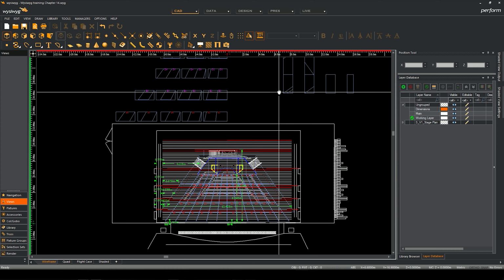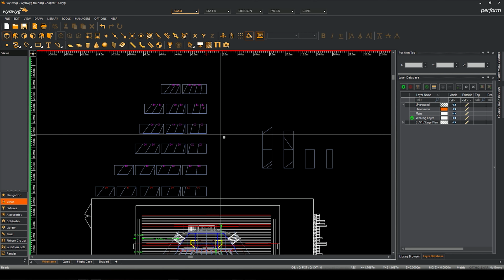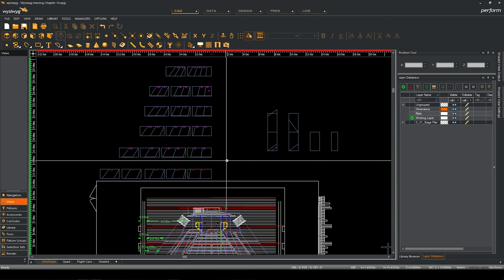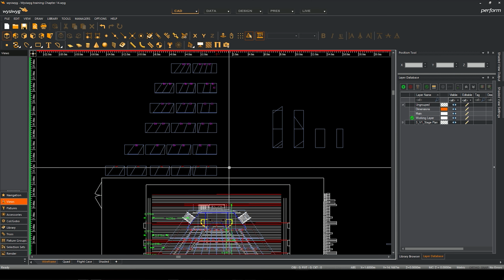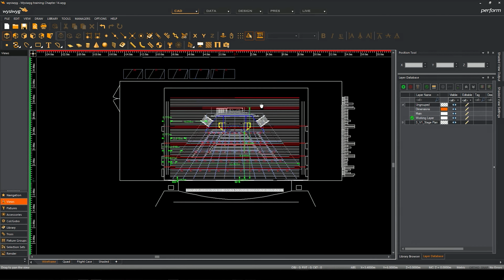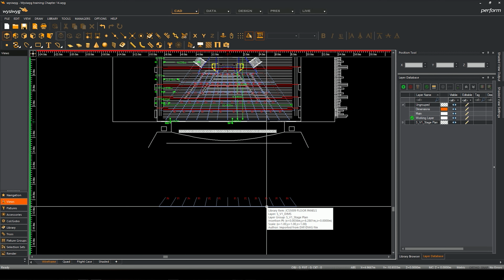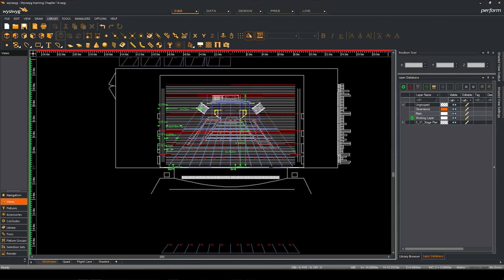You may notice some other objects here that have appeared since I created this drawing. They came in because the layers were off originally in CAD, so we didn't see them, but we can get rid of those later. You just hover your mouse over it, it'll tell you what layer they are, and we can turn those off. So this is layer S_V1_dims for dimensions. So just so you know that.